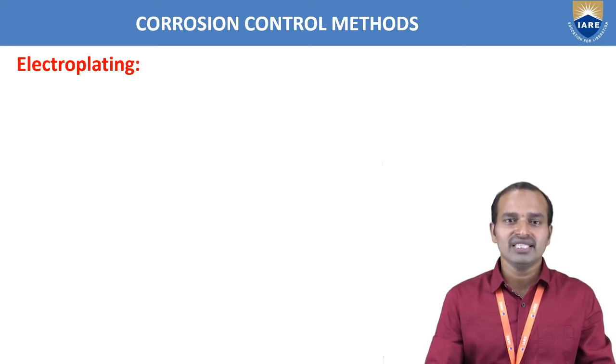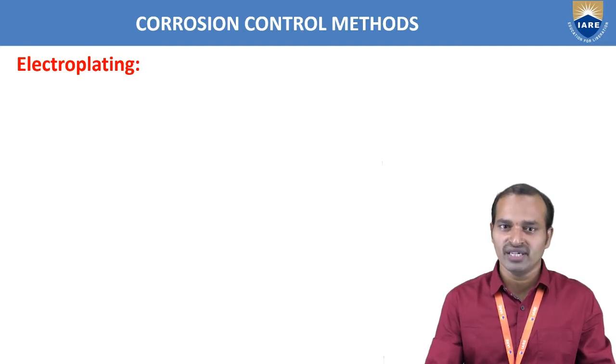So that is called the tinning process. In the galvanizing and tinning processes, first of all the base metal is immersed in acid, that means acid pickling takes place, then a water bath, then drying, then it passes through flux, then the molten coat metal. Lastly, it passes through rollers, and the excess amount of zinc or tin is extracted by the rollers. Then we get the galvanized and tinned sheets. This we discussed in the previous class.